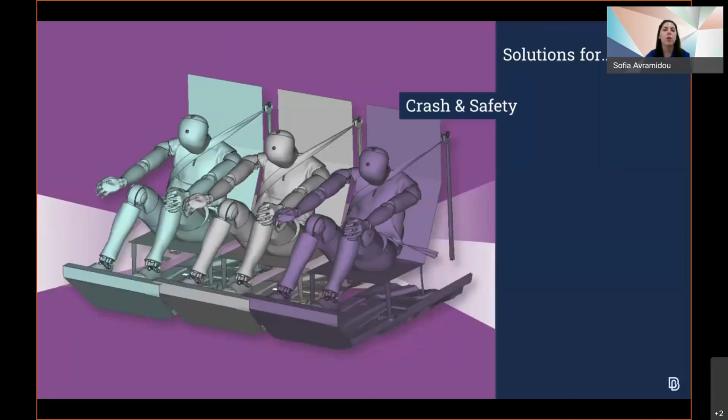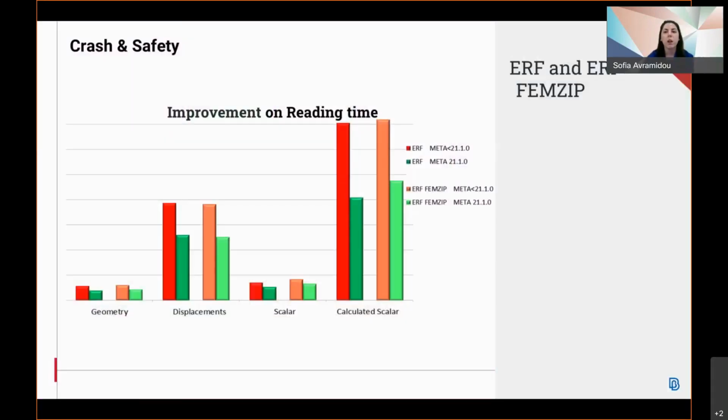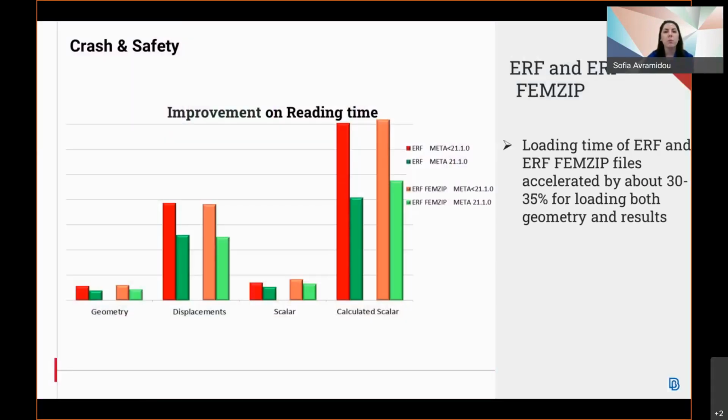Now moving to the various disciplines and starting with crashing safety. Here we've got some major performance improvements in reading time. So the loading time of ERF and ERF FemZip files has been accelerated, reaching up to 30 to 35% when it comes to loading both geometry and results. Furthermore, ERF FemZip version 11 has now been supported.